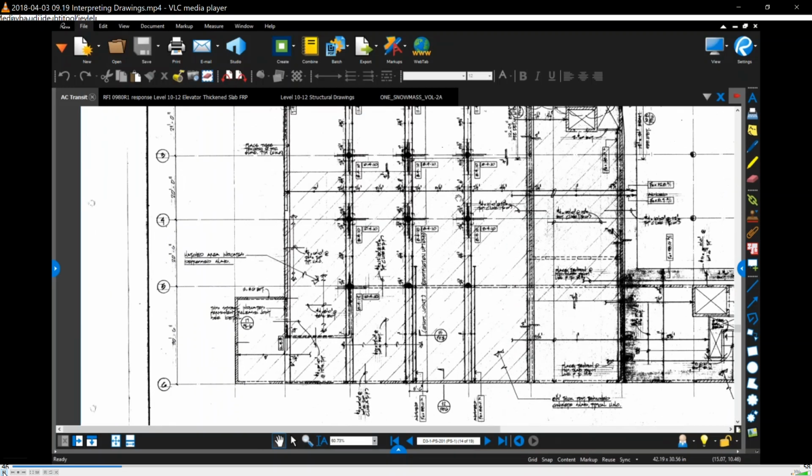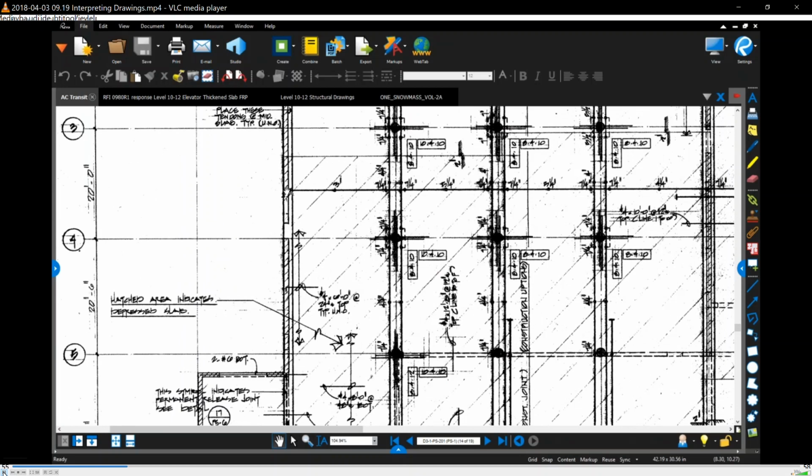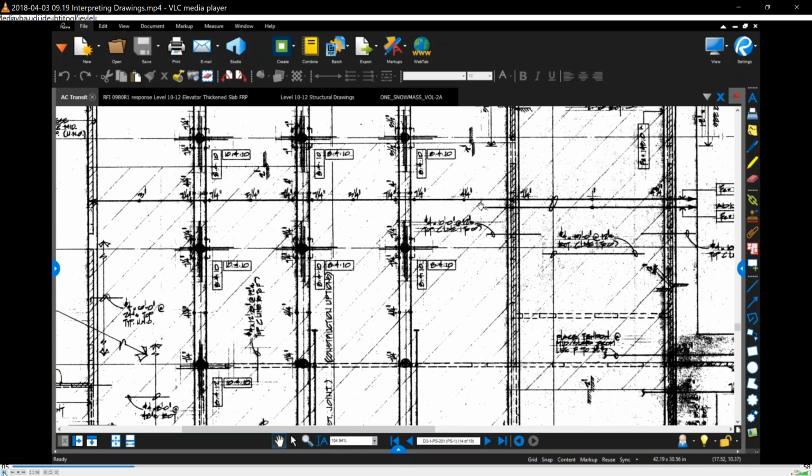There are steel tendons draped, which means profiled. The midpoint is where you stress. This arrow here is a stressing end of this cable, at the midpoint of the slab. You have to stress one end or have a dead end of a cable. The dead end is indicated by a dash here. So that's the dead end of this cable, and it's stressed out this edge of the slab. This dead end and the stressing end are at the midpoint of the slab.